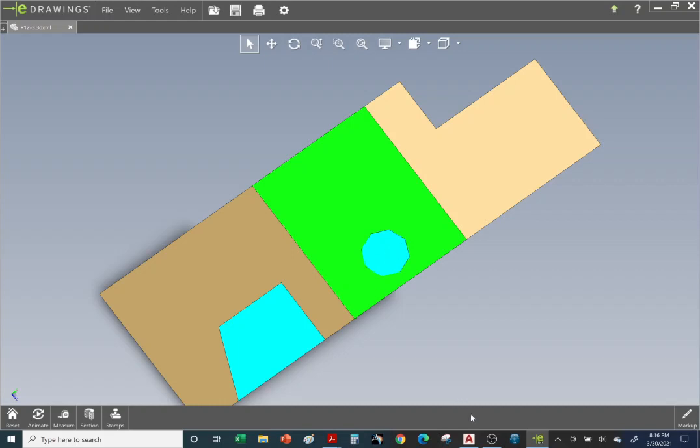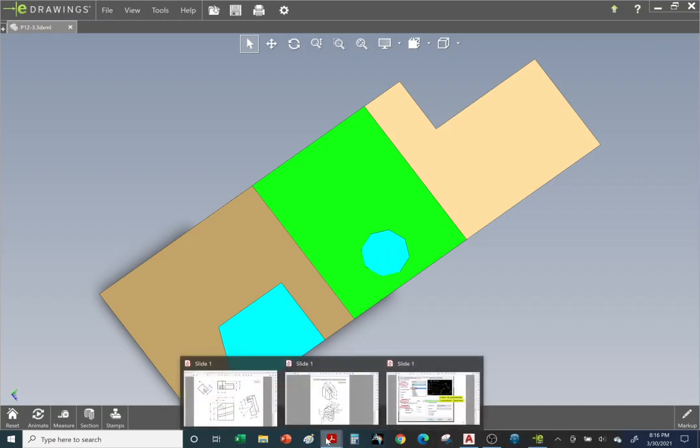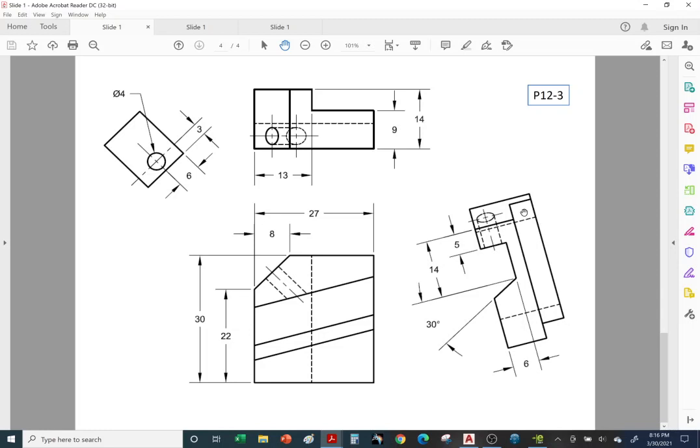All right, so let's go ahead and complete that one. Let's take a look at the answer key. We're going to cheat. Okay, so we got everything here on the right. I think we have everything. I'll double check and see if we didn't miss this object line. And we have this hole that lines up with the hole here, right? And this vertex lines up with this vertex and this vertex with this one. Notice it's all parallel to the axis or perpendicular to the axis of the hole.